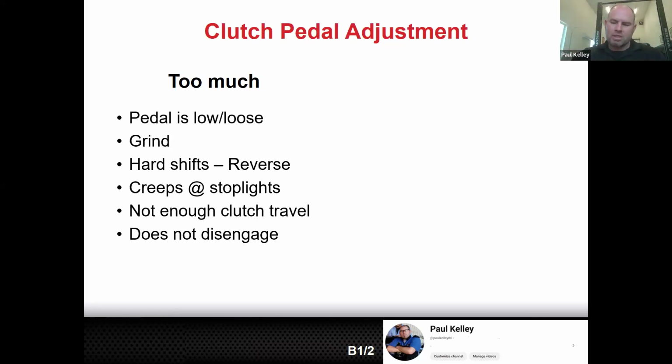And he kind of is, but it's not really that complex. That's why I like to frame this up: remember the release system, all it does is release the clutch, and it can only release it so far. If it releases as far as it's supposed to go and it still drags, maybe it was actually a stepped flywheel issue. So the ASE really gets nitty gritty. Let's say the clutch doesn't disengage all the way, it drags, and you can sometimes measure the throw on the fork. It's thrown all the way, but it still drags. It'd be like, oh, that's got to be a problem with the stepped flywheel. Maybe it was machined wrong. But the ASE would say it was machined wrong, right?